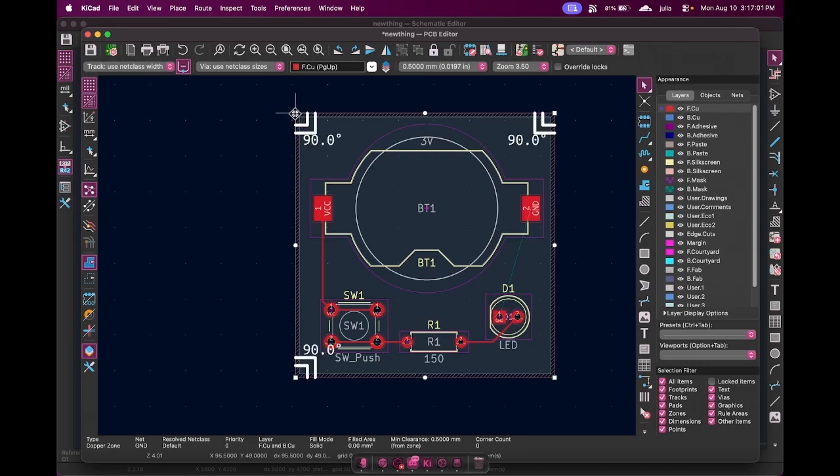I tried to make a feature, but I ran out of space. So your filled zone looks filled in. My filled zone is like filled out. What do you mean filled out? Like it's just red. Oh yeah, no, that's right. You're on the right track. Try to make it 90 degrees if you can. It was a bit tricky. If you need to start again, just delete it and then redraw it and make sure your lines aren't tilted. Make sure they're completely horizontal or vertical.